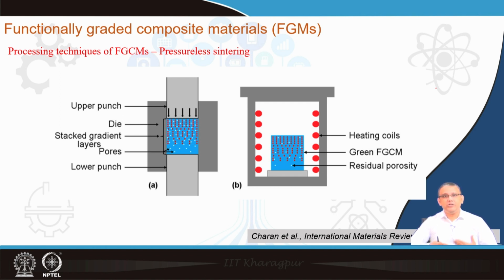But in this case, because you are not applying any external pressure, the cost of the process is much lower. At the same time, because you are not applying any pressure, we tend to have much higher temperature and also a longer holding time. As a result, after pressureless sintering, the samples typically have much larger grain size, which have poor mechanical properties.